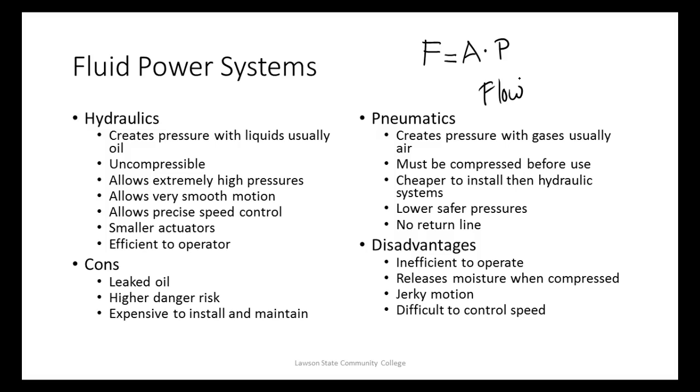So flow, we can control liquid a lot easier than we can control gas. It also allows smaller actuators because it's force equals pressure times area. The planes I worked on ran 3,000 psi on their hydraulic pumps. If you got up into the back of the tail of the plane and looked at the actuators that move these big control surfaces, and I worked on a big airplane, they were only about this big. So they maybe had 2 inches worth of area. But with 3,000 psi, that's 6,000 pounds of force I could create on those surfaces.